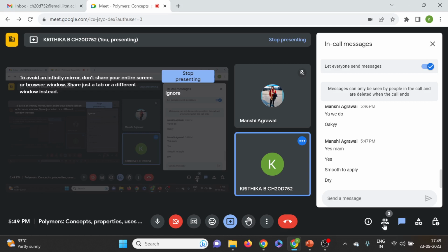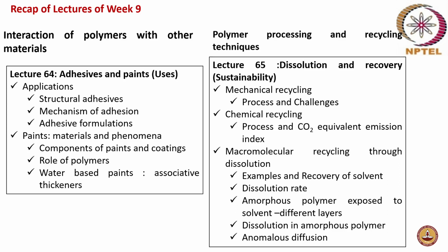During the service life itself, the polymer starts degrading. There can be some oxidation possible, and there can be some chain scission possible. So the mechanical strength of the original polymer and your recycled polymer might not be the same. These are some of the challenges involved in mechanical recycling.